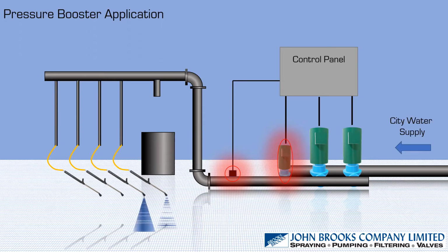Unfortunately, what happens if we start to now increase the flow rates coming from these nozzles or wherever else? Well, that pressure is going to drop even more. So we could have a tuned VFD, so we could start to change the speed of this motor in order to try and keep a constant pressure. Now, again, if this is at the end of a shift and we're really washing down a lot of things, maybe this little jockey pump, as they say, won't be able to keep up.